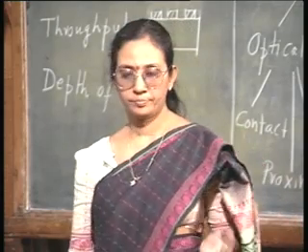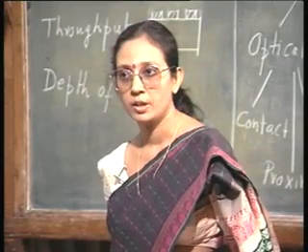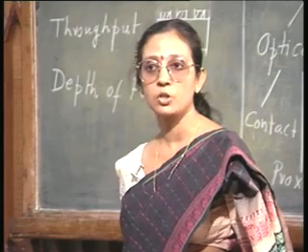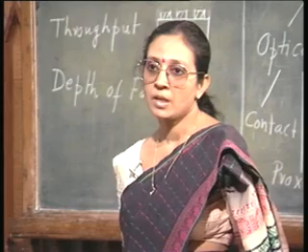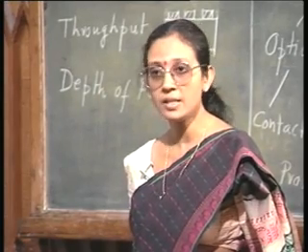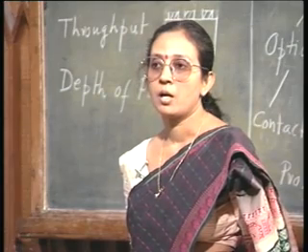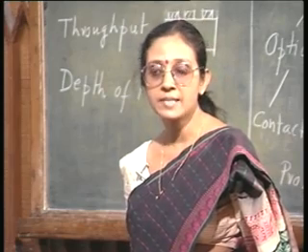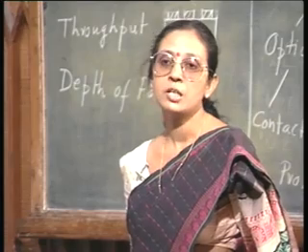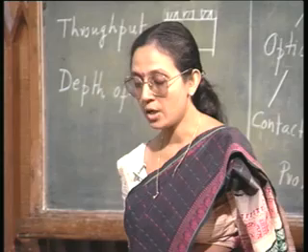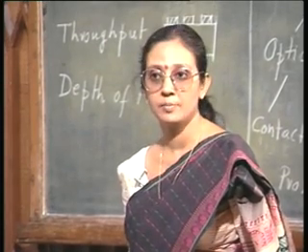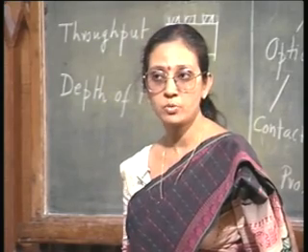Okay. So, we have discussed the process of optical lithography. In optical lithography, I can have three types, three subsections depending on whether the wafer is in contact with the mask or not. I can have two types of resist depending on whether it gets softened or hardened on exposure. And I have also told you what are the basic chemistry behind this hardening and softening. Okay. However, optical lithography has the limitation of resolution, it is 1 micron or at best 0.5 micron if you go to deep UV. Suppose I want to have a really sub-micron technology, then I may have to employ other means, and that brings us to the E-beam lithography, which we will be discussing in the next class.